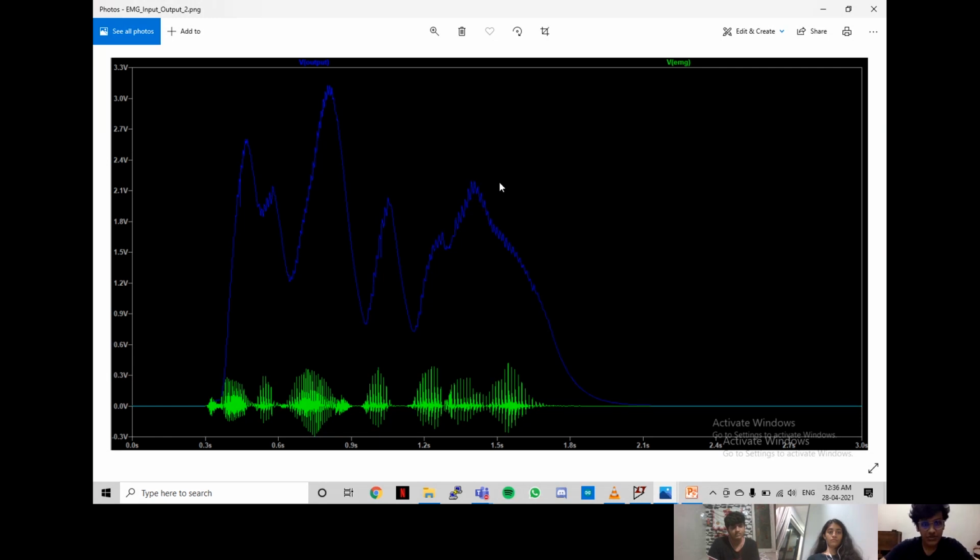Now, thresholds are set according to which the Raspberry Pi Pico will produce an output, which is given to the DC motors, and the DC motors are connected to the axle of the wheelchair. Hence, it will move. Now, the Pi Pico cannot drive two DC motors, hence we use a motor driver module, which isolates the DC motors from the controller,